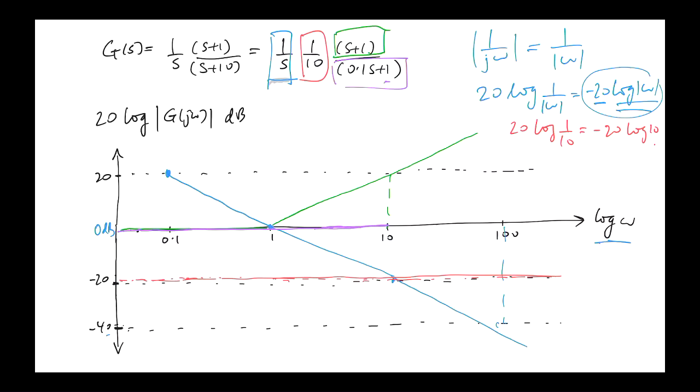Okay? Because if we evaluate that at j omega equals 10, the magnitude we're getting is equal to root 2. So it won't actually be sitting at 0 dB, it'll be at 3 dB. But as a straight line approximation, we keep it at 0 there, and then it will kick down at 20 dB per decade. So by the time it gets to 100, which is 10 times 10, it'll hit minus 20 dB, and then it will keep going.